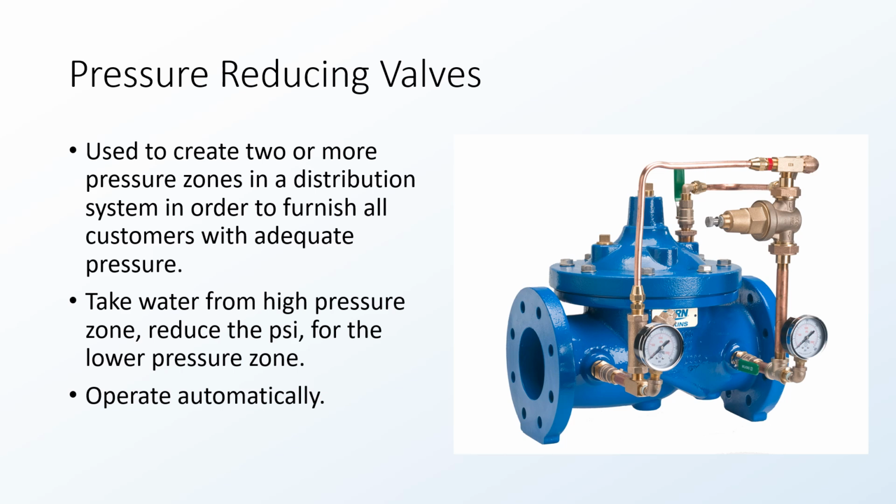And then they have other types, CRAs and CRLs, that will control the opposite, if you're trying to control upstream pressure. Anyway, there are many different ways to plumb these, and like I said, you should get your chance to get your hands on these. They are a lot of fun to work with.